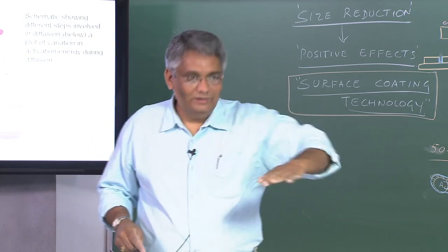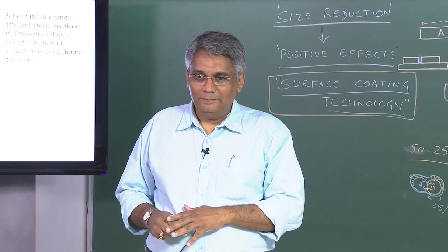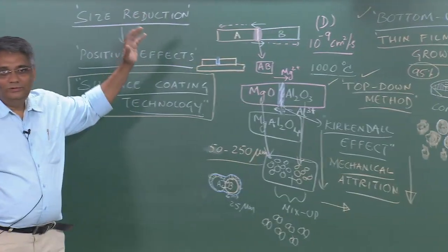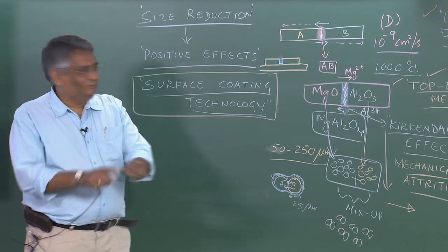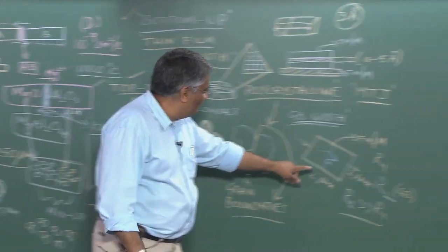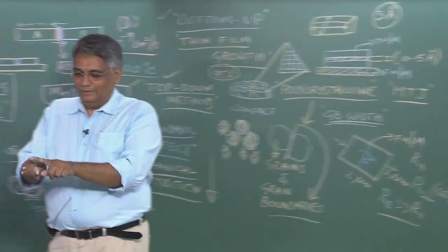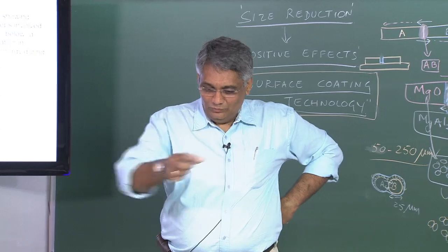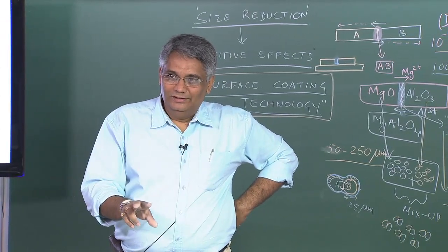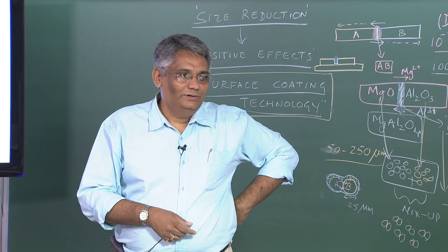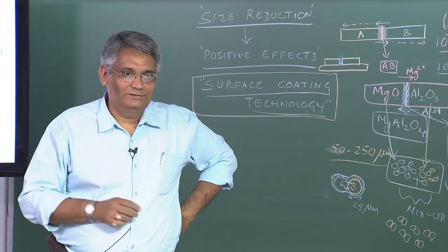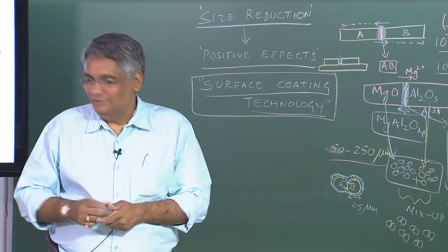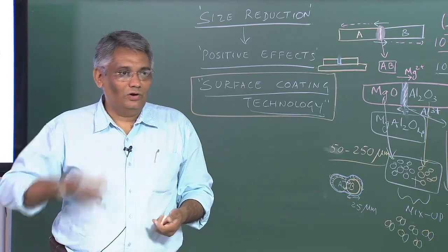You have to go for the fabrication method. So you get a regular single layer film, right, and selectively remove a few atomic layers. How many atomic layers have to be removed in order to get to this range? 2 to 3 unit cells have to go, right? Now to remove unit cells within 10 to 15 angstroms, you need a beam which is of that size. So you need a focused electron beam or a focused X-ray source. So you can selectively etch out, knock off atoms.